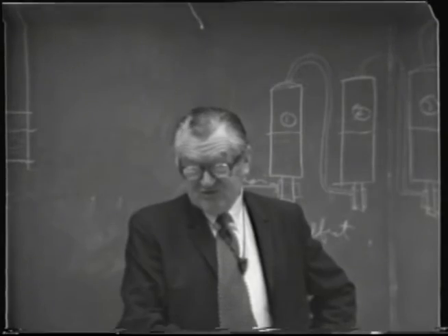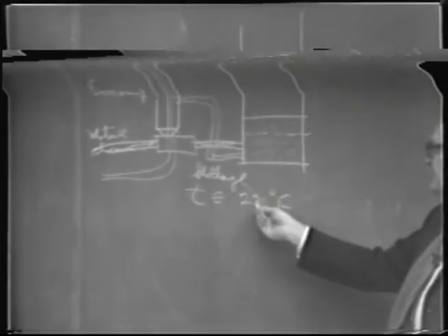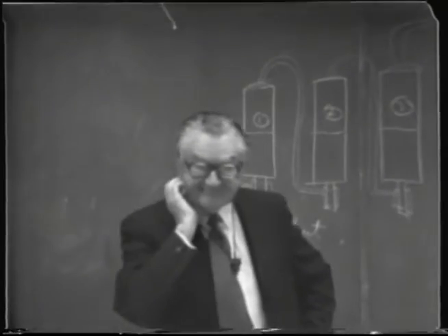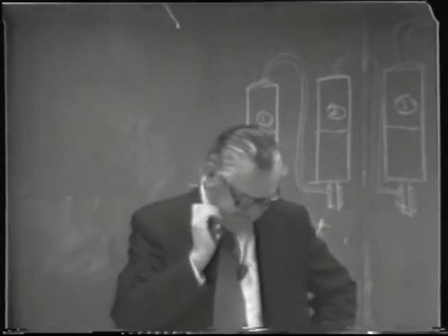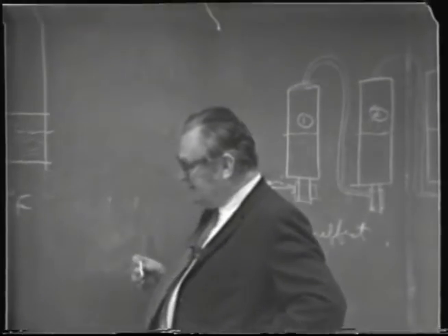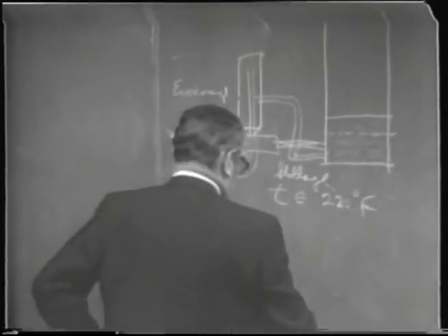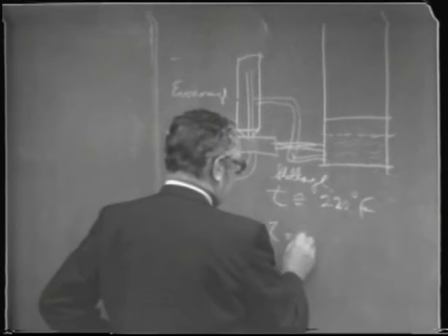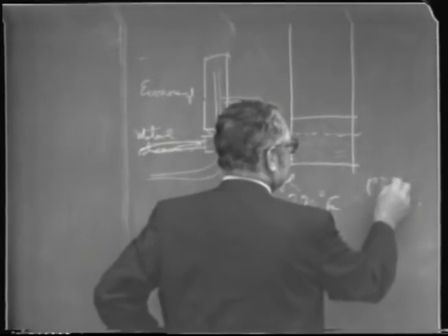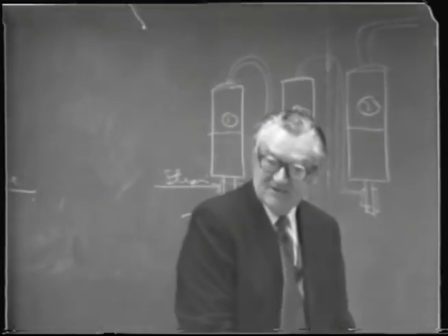At some reduced pressure, this stillage here, which has a saturation temperature of 220 degrees Fahrenheit, because it has about 3 pounds per square inch gauge pressure at the base, as a typical case. When it's reduced down to some pressure, if the temperature might get down to 175 degrees Fahrenheit, we can look up what the saturation pressure would be by looking up steam tables.